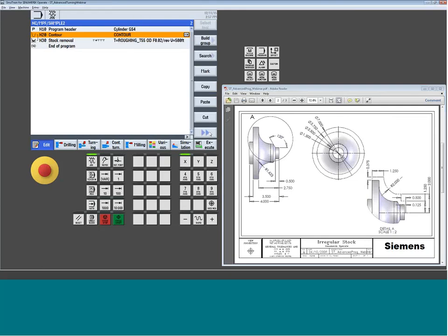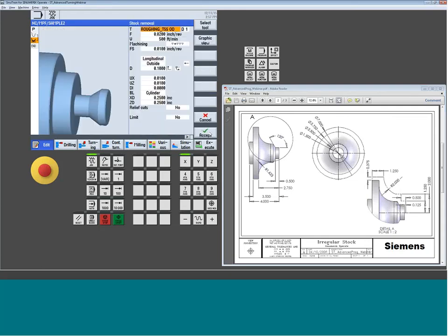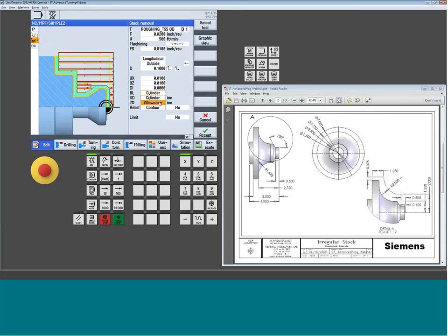So now what you need to do, just like you did before, is associate it to a stock removal cycle. But in the stock removal cycle now, you're going to come down to BL, and BL represents the stock that we're machining from. Your blank description is the B for the BL. And we're going to toggle this to allowance. And allowance now gives us an X and a D value. And that value is how much material I'm adding to this surface shape.